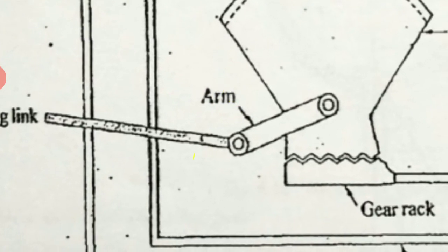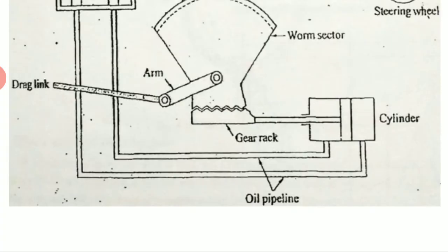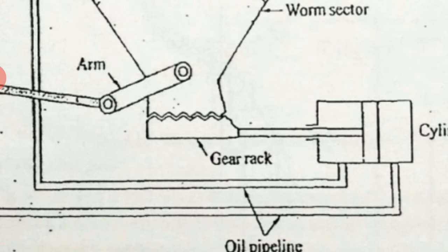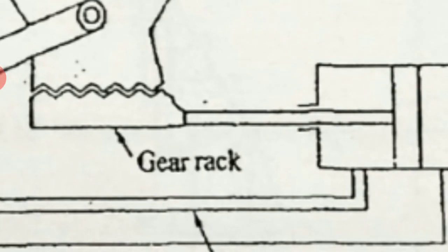So we'll actuate this automatically. What happens from this pipeline is that axially, together with the distributor valve, the axial movement will admit compressed air or oil into the booster cylinder. Automatically it will enter into the booster cylinder through the pipeline. The piston in the booster cylinder will then turn the road wheels via the gear rack.